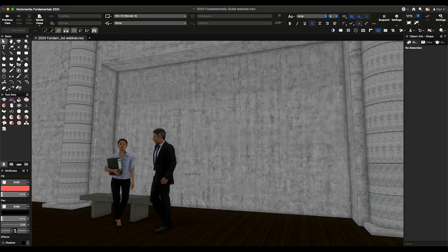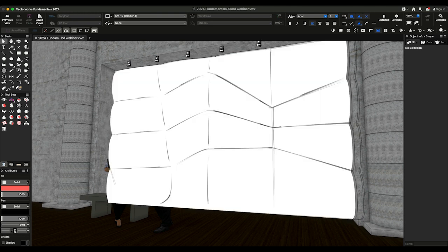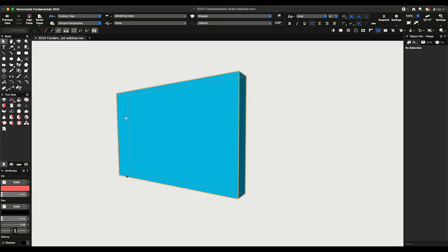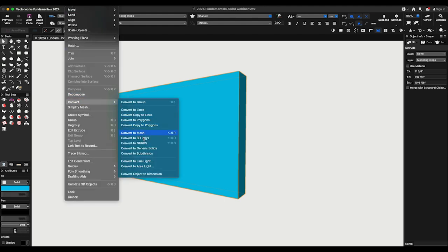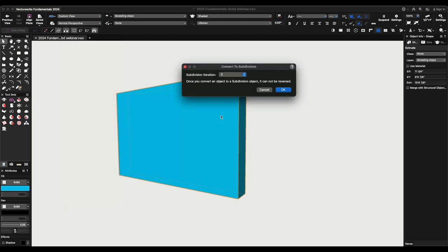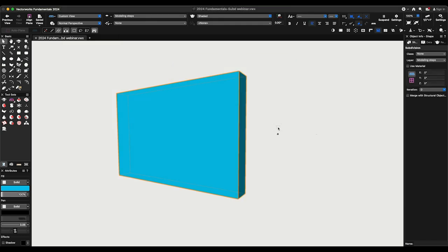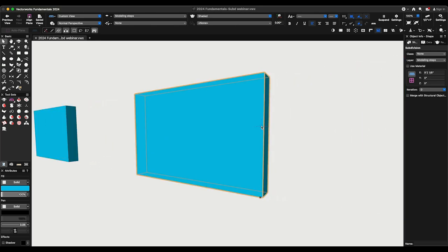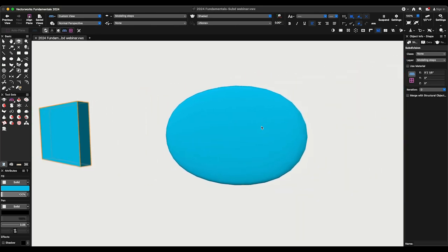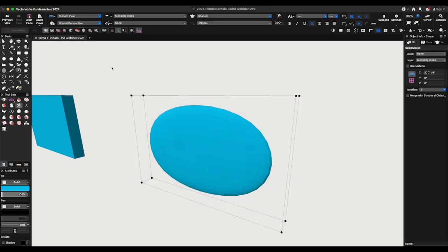Okay, by now, I guess you want to see some action. So let's pretend we want to win a commission for an installation art. And here's a sketch of the artwork I have in mind. I'll start a project with a simple block, an extruded rectangle. Then I'll select it and convert it to a subdivision object. If I leave it as iteration 0, I'll keep the same shape. But I know I needed a 3, and you'll see why. I know I need to flatten the end faces.